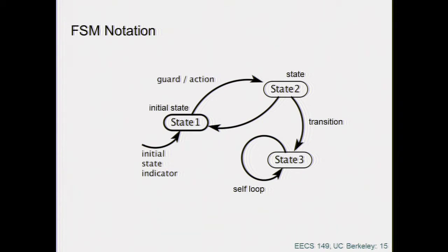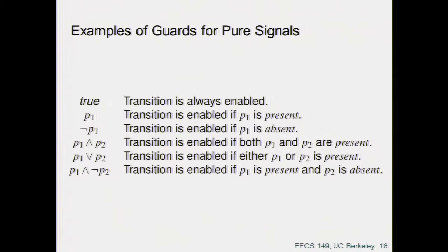But very often, when you do designs, you give the states not a number, but you give it a semantic notation. So maybe I'm standing, I'm moving, this kind of thing. So the states are not labeled state 0, 1, 2, 3, 4, right? Also because if you want to document what this finite state machine does, it's better to be descriptive, right? So every state should tell you what the meaning of that state is. And so in that particular case, unless you specifically indicate what is the initial state, then there is no way that you can infer it by looking at the label of a state.